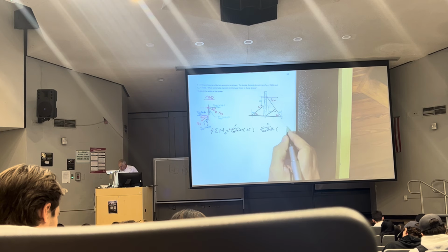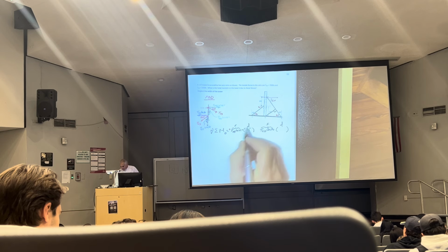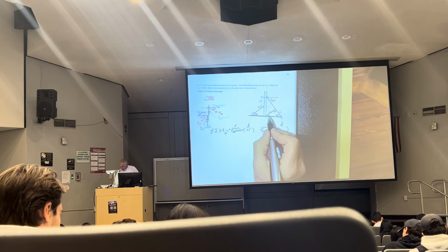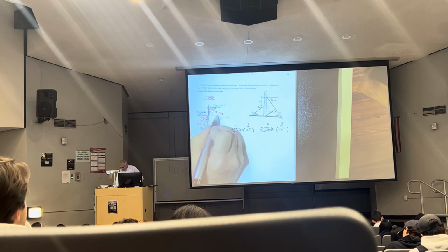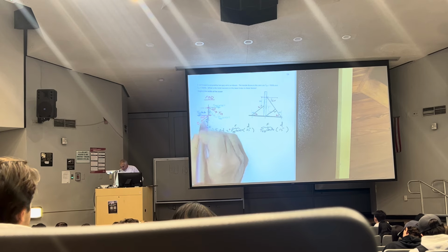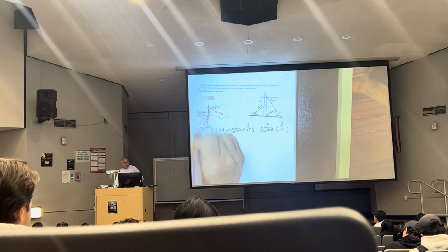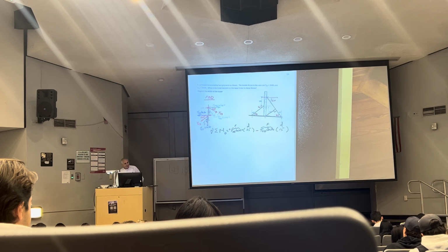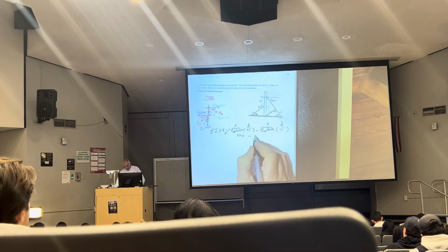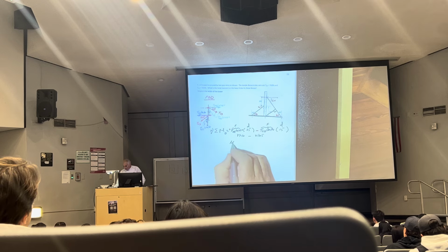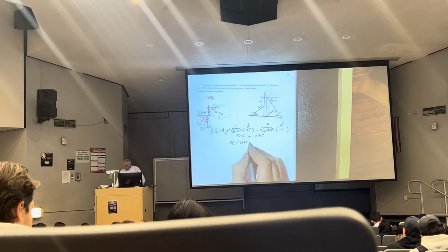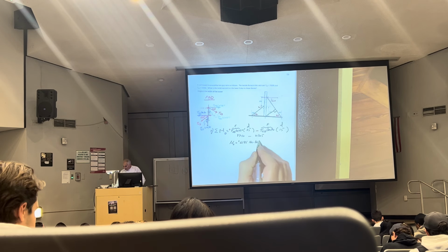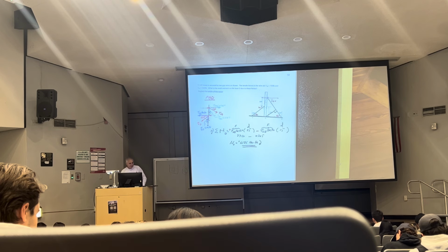Next, I'm going to say TCD cosine 70. That's the force. I need the distance. The distance from here to here is 15. Now, let's move this all the way back to here and go around O. What do I get? Counterclockwise. Oh, that's a negative. That's 8750 minus 2565, moment about O is equal to 6185 positive. So this is pound-feet, clockwise.